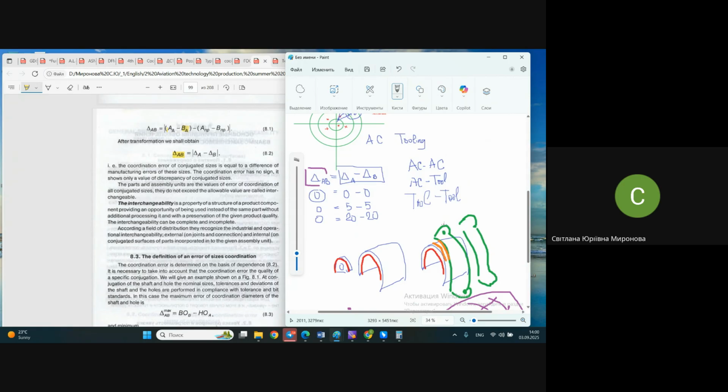Why? Because our object has a peculiarity. This peculiarity I have already perforated your brains with. A peculiarity that is responsible for specific methods of coordination: low stiffness. Airframe components, as a rule, are of great overall sizes, but they are thin. And as they are thin, they are not stiff enough, considering their sizes. They are trembling in hands.